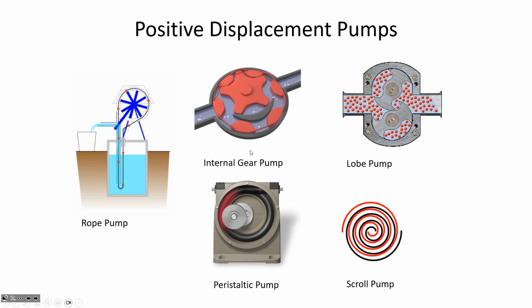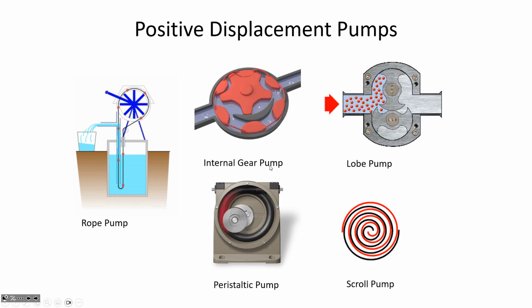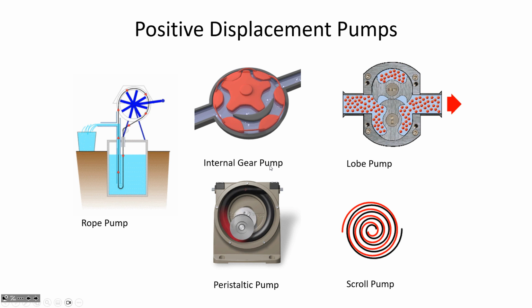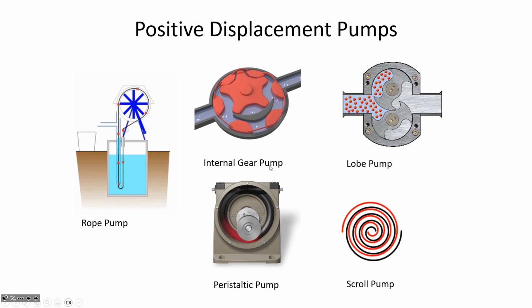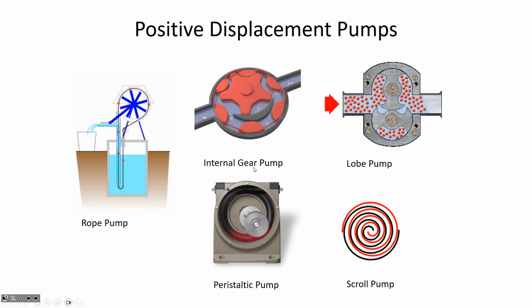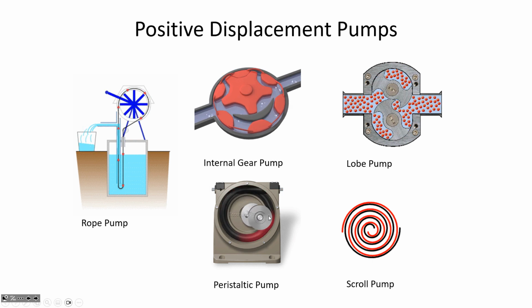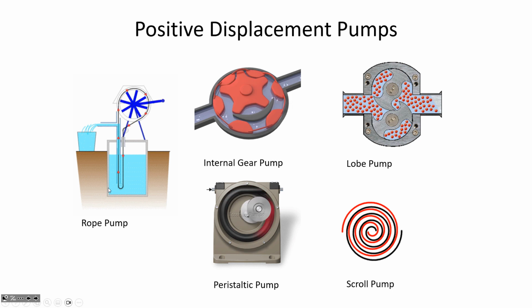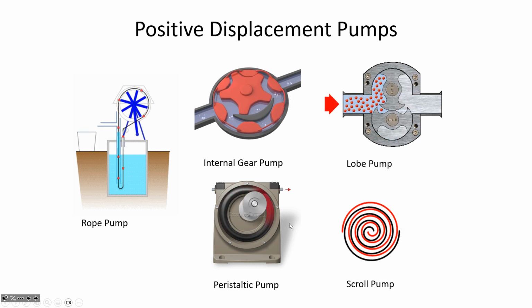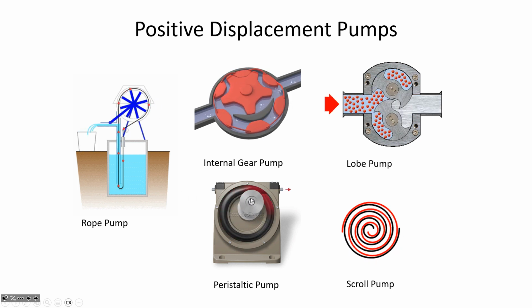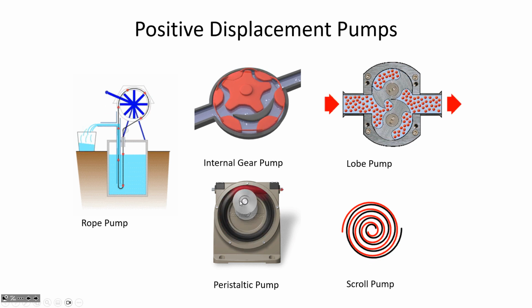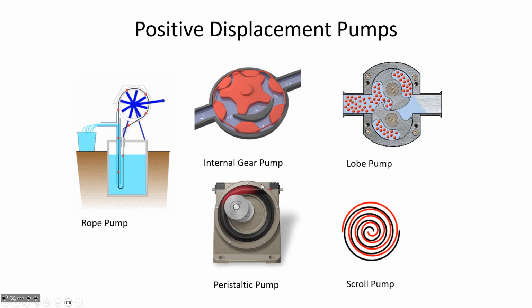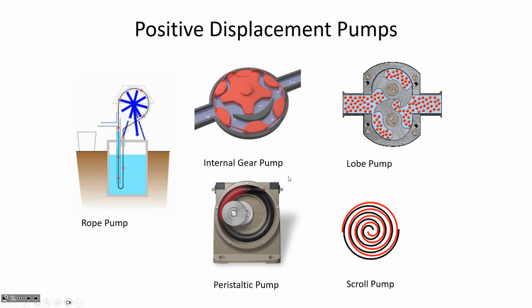A peristaltic pump is something that you'd see in a lab, like in a wet lab where they're doing chemistry analysis or environmental sampling. It's common to see a peristaltic pump. It's a flexible tubing. You'd have a plastic tube that's threaded through a circular conduit, and a roller is pressing the tube together, squeezing the tube, and forcing the water out through the discharge area.